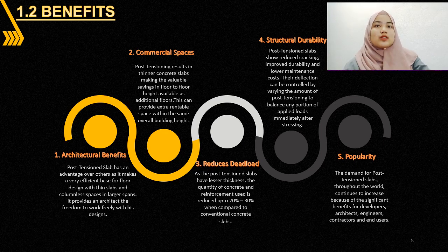Number 2 is commercial space. Post-tensioning results in a thinner concrete slab, making the saving in floor-to-floor height available as an additional floor. This can provide extra rentable space within the same overall building height.